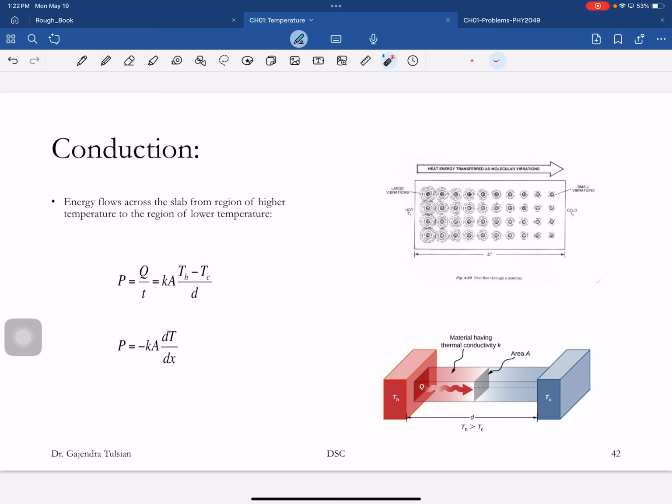Why are we interested in this? Yeah, we calculate how long something can be in contact. Right now it's hot outside. We're keeping this place cool. There's heat flowing in through that wall, and it's costing us money to keep this place cool. So if we can decrease the thermal conductivity of the walls, our cooling bills will be smaller.